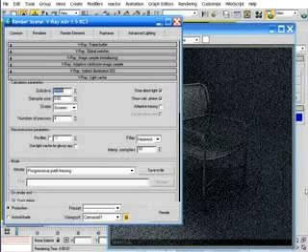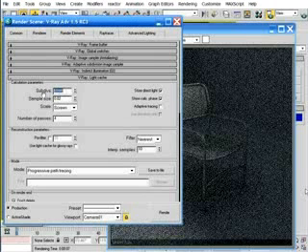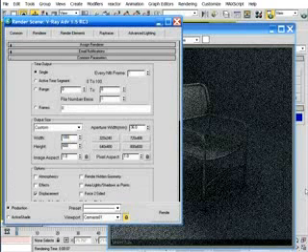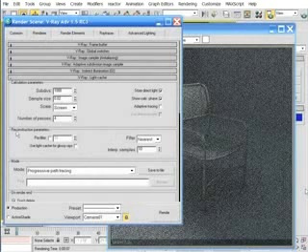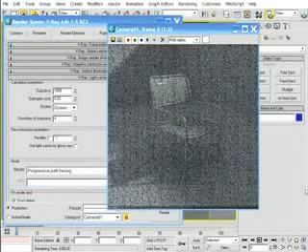And to put that into perspective, consider the following example. If you use a subdivision value of 1,000, then of course the number of rays being traced is 1,000 times 1,000, or 1 million. Likewise, if you render an image 1,000 pixels by 1,000 pixels, then of course your image will have 1 million pixels in it. Therefore, using a subdivision value of 1,000 on a rendering of this size means that you're going to have one sample ray taken for each pixel. If you render with such a configuration, clearly the image is not a good one.